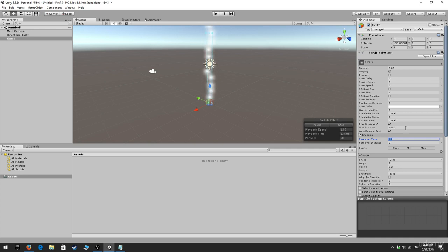And right now we just need to edit all of these properties in the inspector tab right here, clicking this particle system. So we need to reduce start speed, because this is not a rapid fire, this is an ordinary fire, and we're just going to set speed to be maybe 1. The next thing we can change is rotation, because every fire has its own flip when it rotates. Imagine how fire goes. It rotates a little bit, and that might be around 50 or 60 degrees. So we're going to set start rotation to be around 60. Okay, that would be good.